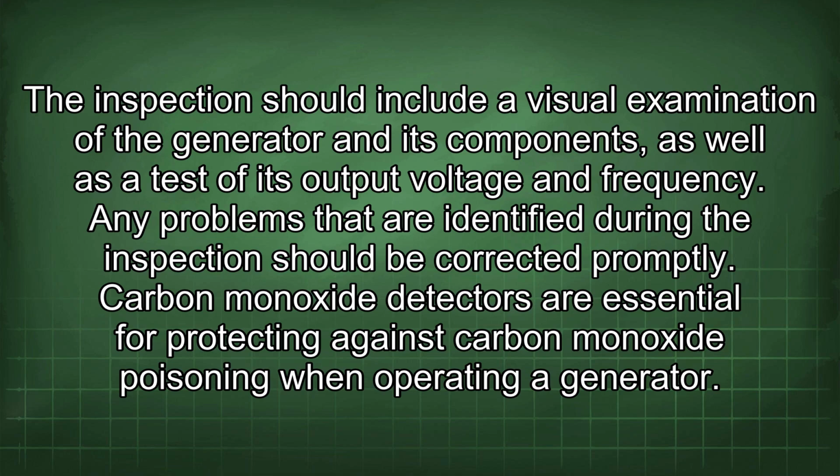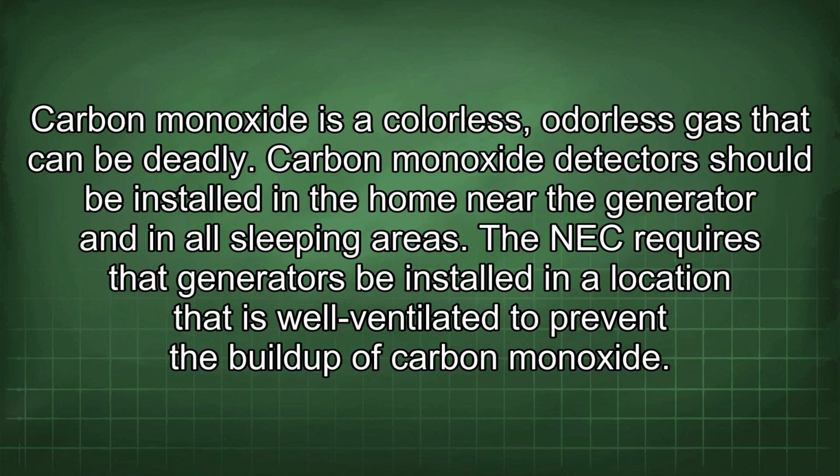Carbon monoxide detectors are essential for protecting against carbon monoxide poisoning when operating a generator. Carbon monoxide is a colorless, odorless gas that can be deadly. Carbon monoxide detectors should be installed in the home near the generator and in all sleeping areas.